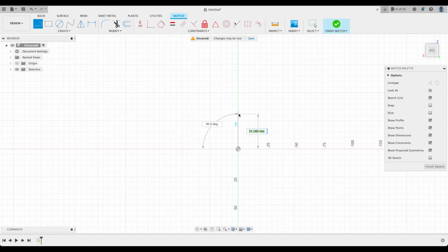Again, I've got here a length, so if I want to type a specific length in, let's just do some right angle turns and corners before we start getting any angles. So let's say I wanted to make something here, let's make it 30 millimeters long, and then I'm going to click with my mouse, but I haven't entered anything like this. I'm now just moving along. Let's say I want to make this 15 millimeters, and it's still at 90 degrees, and I'm going to click with my mouse to set that dimension.